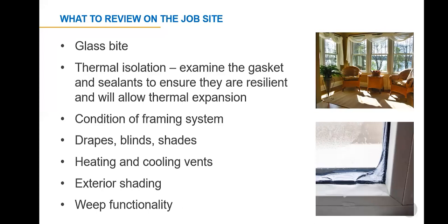So when you're on the job site, what do you want to review? The glass bite, how much is it? Thermal isolation. Examine the gasket and the sealants to ensure that they are resilient and will allow for thermal expansion. What's the condition of the framing system? Is it old and is it damaged? Drapes, blinds, shades? Are they ventilated? Do they allow the heat to escape? Heating and cooling vents, are they pointed towards the windows? Exterior shading, look for trees, homes, buildings. Imagine the position at different times in the day. Will shadows form on the window? And for the weep functionality, look for clogs that will cause rainwater to accumulate in the frames.